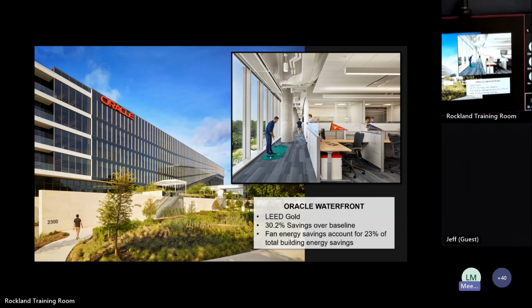For office space design, usually latent load is driving your primary air, so you're really not down to your ventilation airflow rate. We'll go into this in detail in the software section in the afternoon, but you'll see where your minimum ventilation might be 0.2 CFM per square foot or less, but you're actually up to 0.3 or 0.4 CFM per square foot just to take care of the latent conditions in the space.